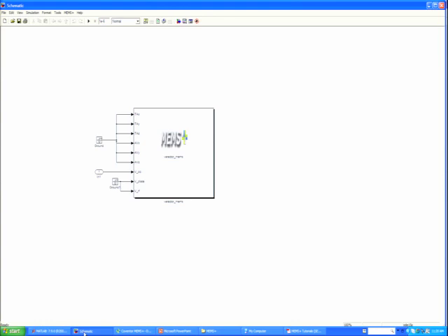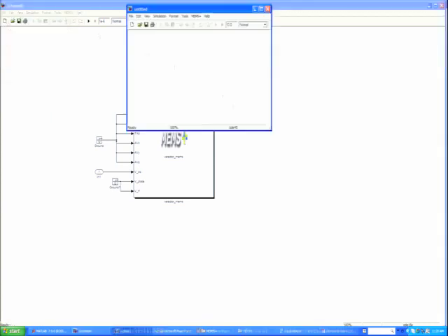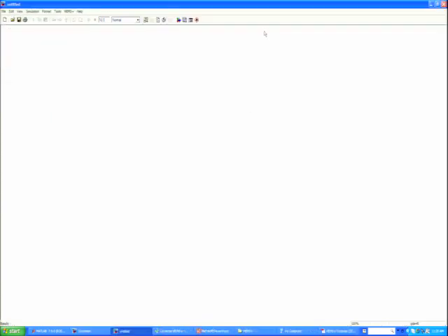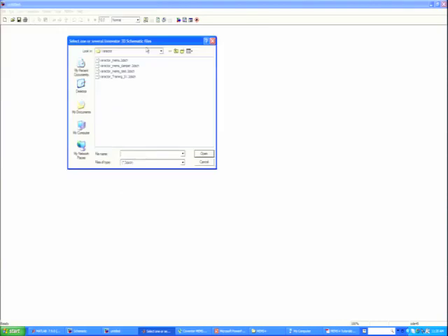Okay. So how you work in MATLAB is, let's just open a new model. I'll show you how to bring it in, then we'll just use the schematic. I say new model, a blank Simulink window pops up. Now when installed correctly, you will see a new tab that says MEMS plus. Okay, that is when all the paths are defined correctly. So I can say MEMS plus, import MEMS plus model, and I can now choose which 3D SCH file I want. So I have multiple versions. I'm just going to use, let's say, the first one.